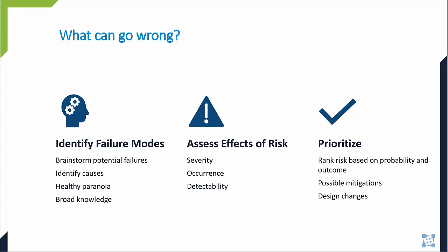So we have to think about what's the severity, how likely is it to occur, what does it take to make it occur, and will we notice if it occurs? If I'm leaking fuel or my fuel tank's low or I have an oil leak, will I know before it gets critical? On cars, really good cars, I would say, have a rich set of instrumentation on the dash, and they tell you things like the temperature of the engine, as well as maybe the temperature of the oil and the oil pressure.